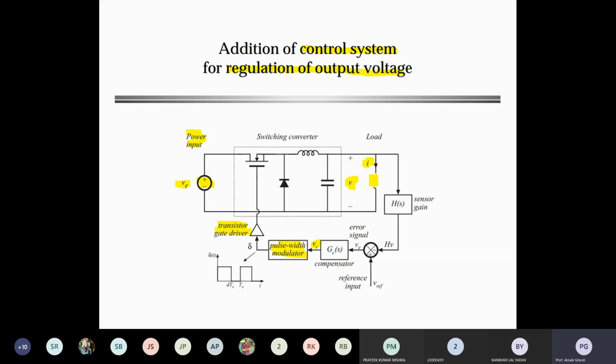If you connect another resistance in series with that load, the current may be the same but the voltage may be different, because exactly that drop will be there for this load. Then an additional drop will be there for that additional load. That drop adds directly, but you have to maintain the output voltage V fixed. So again the concept of regulation comes in, and it will modulate the pulses of the switches and keep it fixed.